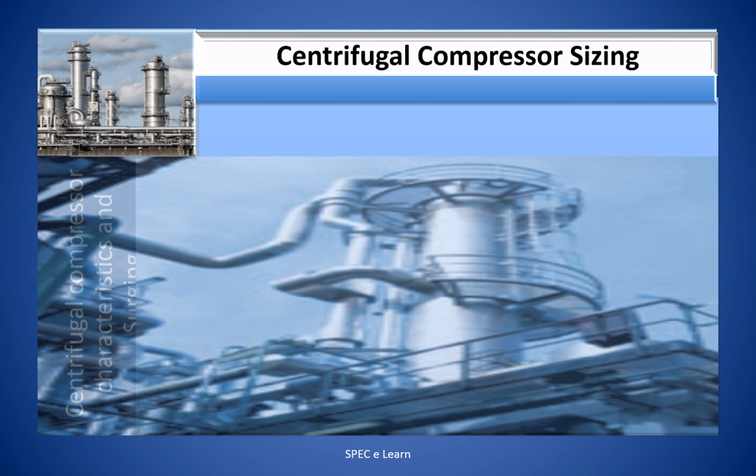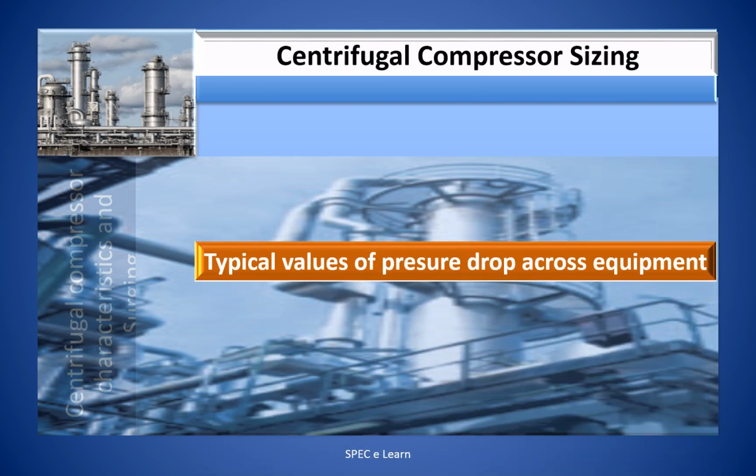Design parameters such as tower diameters in the case of mass transfer equipment, tube and shell diameter, and number of passes in the case of heat exchangers are adjusted to achieve the pressure drop specification values. Hence, it is available and extracted from the process design document. You need the number of trays, height of packed beds, height of dry bed, etc. to estimate the pressure drop.